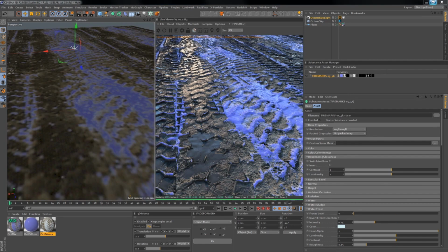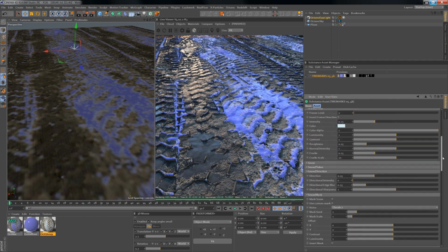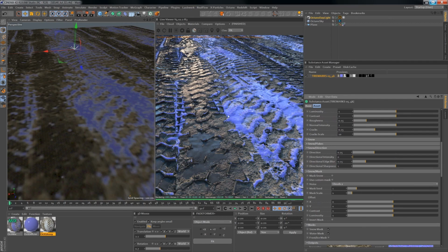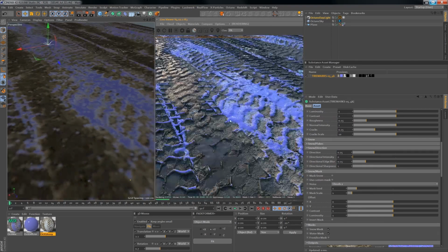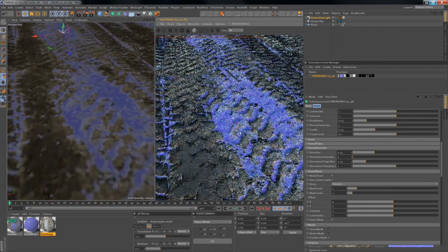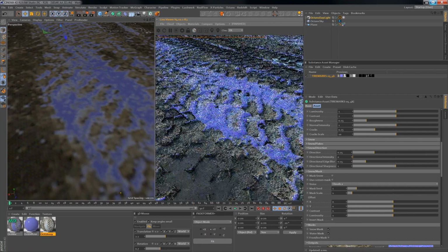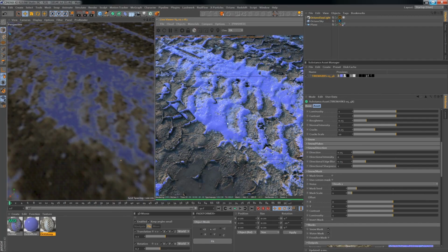We do have a nice additional feature, which is a direction mask. This makes it possible to use this substance also for walls, not only for floors. And you can also simulate kind of wind that makes the snow appear on one side of the height field and not on the other side. So we have this snow direction, and now we turn on the direction intensity.